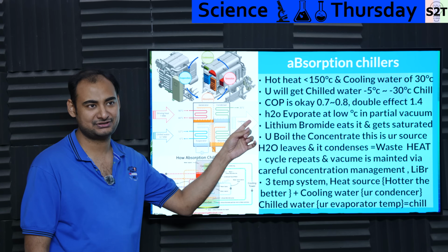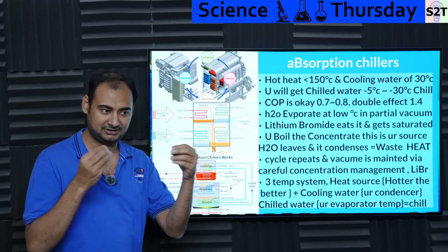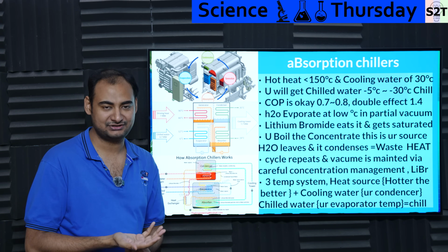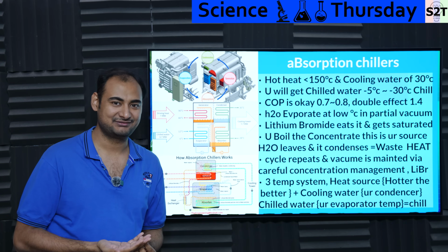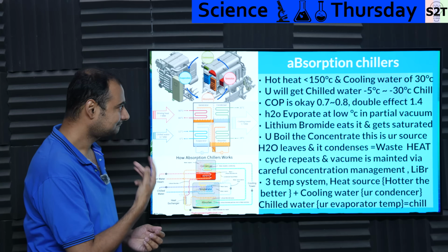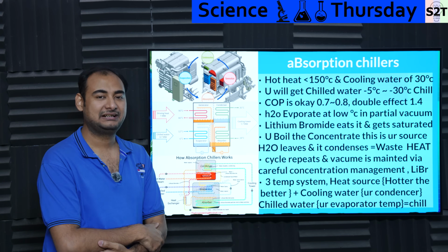And some places, you do not want to do a generator. These things can run 24/7 for a very long time, while your fire boiler can also run 24/7. Generators are not designed to run 24/7 for very long durations. So absorption chiller is a very clever utilization system.